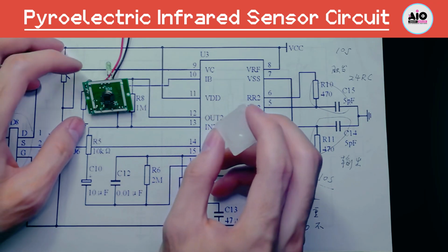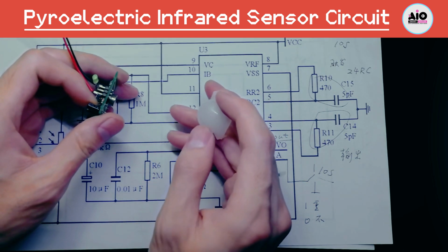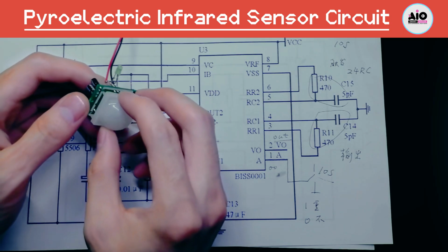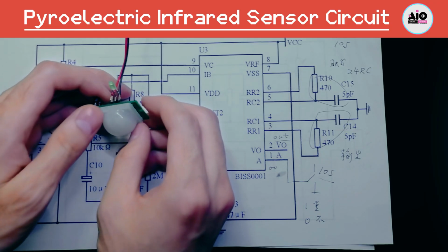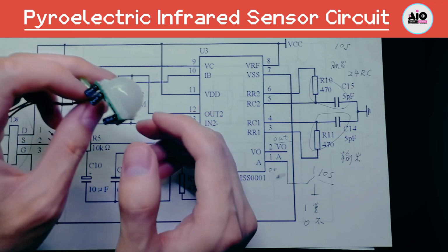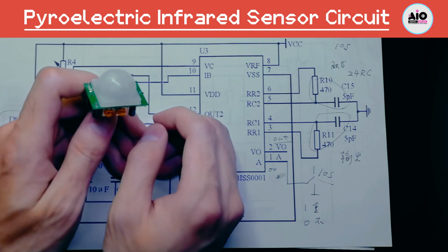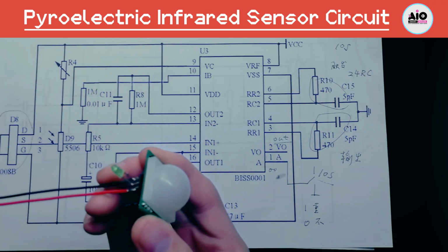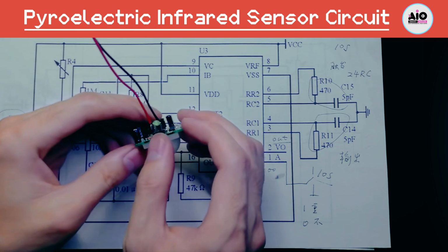In order to improve sensitivity, this kind of lens is usually used in front of it. This kind of lens is called a Fresnel lens. It has a specific angle in its parameters. It will converge the surrounding infrared radiation into a certain angle range to enter. This is the window of the pyroelectric infrared sensor, so its use is like this. In front of the window, a lens will be added to focus the infrared light.